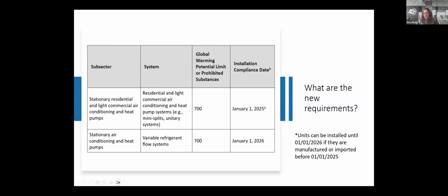Okay, that sounds good. And then I've got one more request for comment on heat pumps. You said it was best for when it's hot outside. Yeah. These refrigerants have a great capacity for heat rejection when it's really hot outside. They are approximately equivalent to the efficiency of A1 refrigerants when it's cold outside, so in a heat pump scenario.